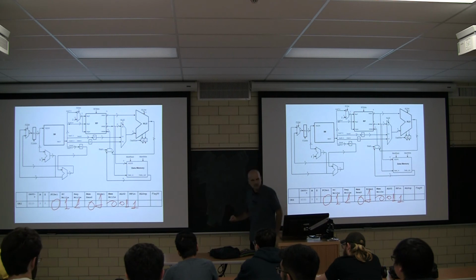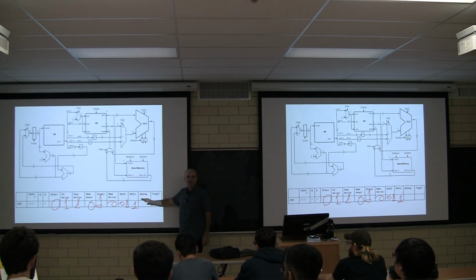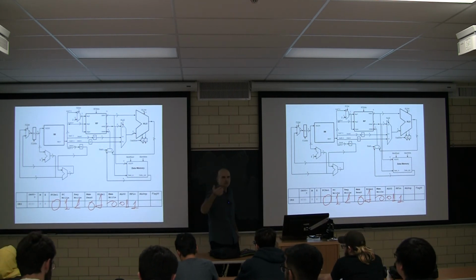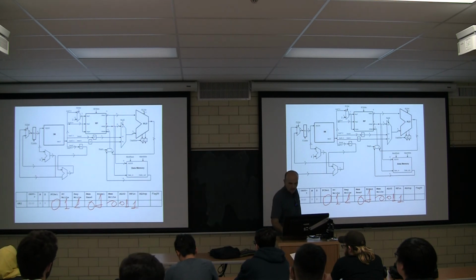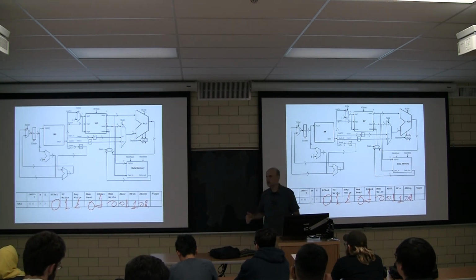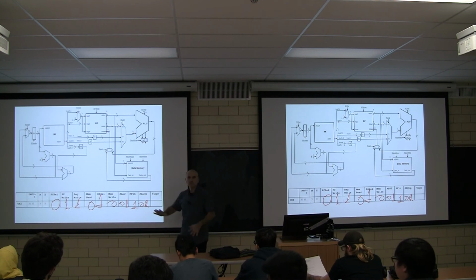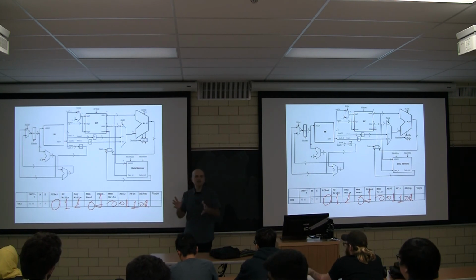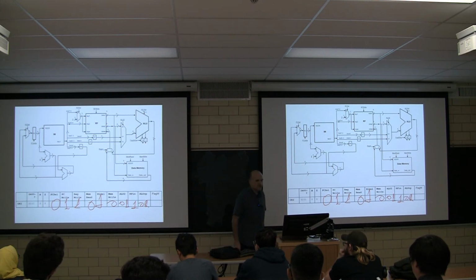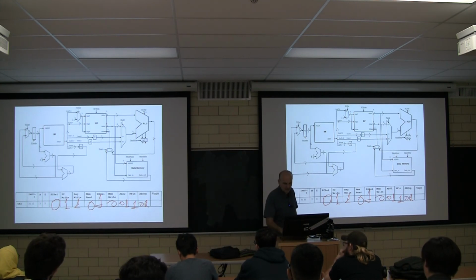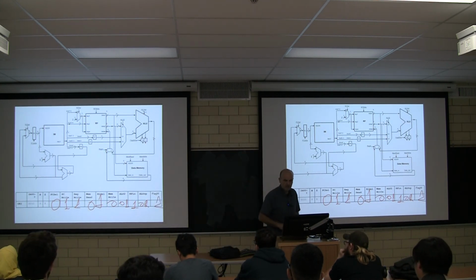Sorry for the confusion today, I've got to get my act together. I'm a bit distracted. So ALU op, I don't remember what the encoding is. We have to flip the slide. So let's write ORI, OR. That's supposed to be an OR, by the way. It is a 3-bit value, which is what we defined on the slides before. And finally, should we change the flags? Yes, because ORI changes the flags. And that's supposed to be a 1.